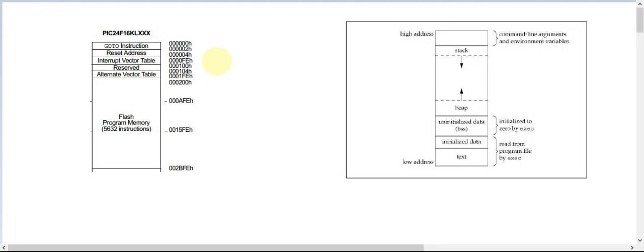Okay, hello guys. In this video we're gonna pick up where we left off in the last video. In the last video we said that when you power up your microcontroller, the processor loads the startup code from the reset vector on your flash memory and starts running this code. We said that of the things this code does, it initializes the stack and the heap. In this video we're gonna talk about the stack and the heap and how they are actually connected together.